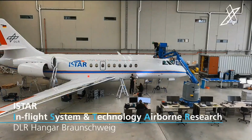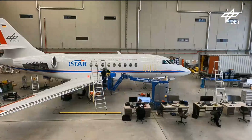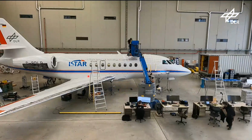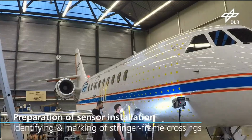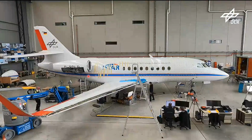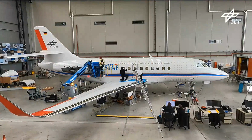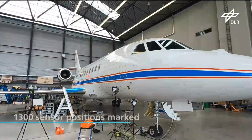In the beginning we had to mark every single sensor position. This took us about 2.5 or 3 days. We weren't able to estimate the positions of the stickers by measuring, but had to identify the rivet crossings on the surface of the aircraft.